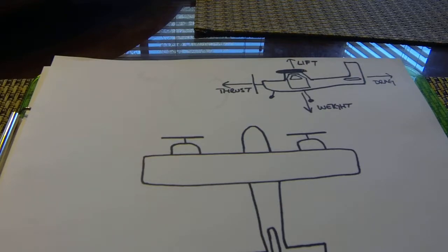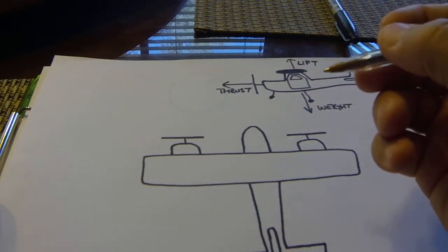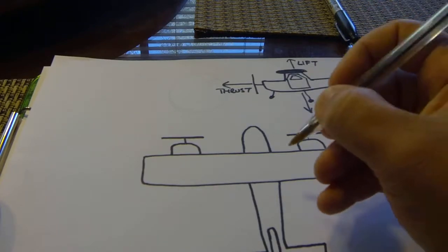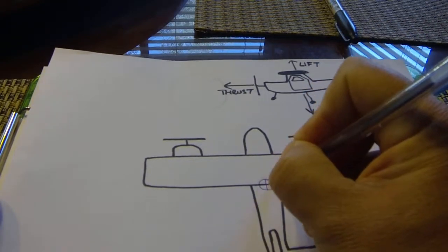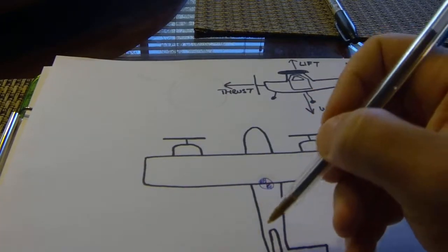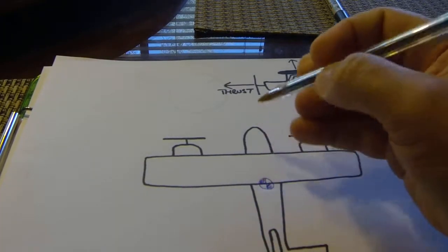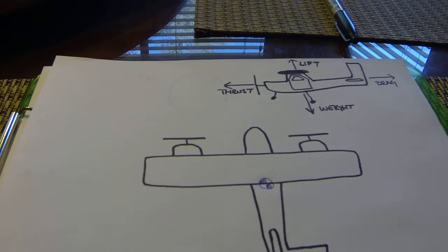So the first criteria, which is all laid out in 23.149, it talks about how to determine VMC. The first thing that we want to talk about is our center of gravity. According to the CFRs, the center of gravity needs to be in the aft location. We talked about that last time. Why the aft, right? From our rudder to the CG is the shortest arm. When it's in the aft position, it's the weakest the rudder is going to be.